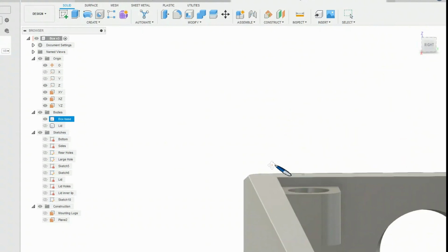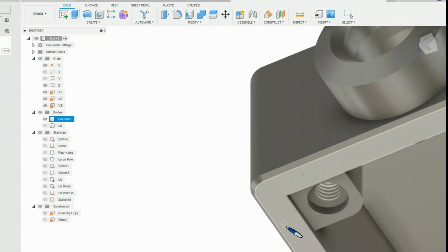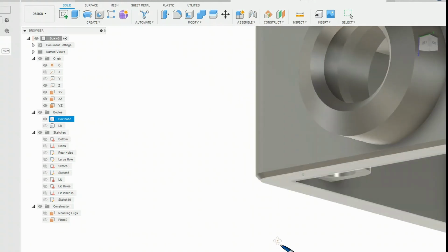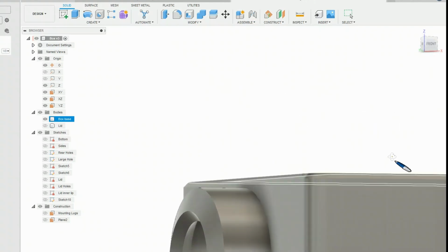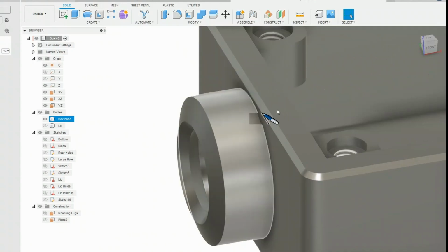And now I have this unusual profile that I've drawn on there, which might be to fit something very special. It just gives you the idea of how we can revolve around a shape. I could also have done that around the top edge. It didn't have to be the circle. It can basically follow any closed edge.